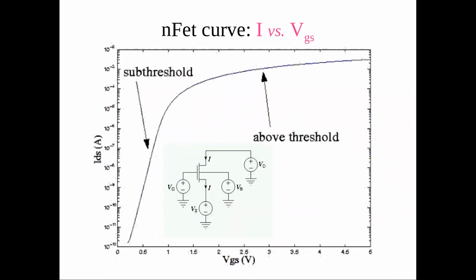On the other hand, if you have the same fluctuations on the x-axis between, I don't know, 0.5 and 1, you have some noise here, your output current will change by like 3-4 orders of magnitude. The effect is going to be huge. So you're going to be very, very strongly affected by noise in subthreshold, and less affected by noise in above threshold. That's why standard textbooks say we care about precision. We're going to do our circuits in this region of operation.